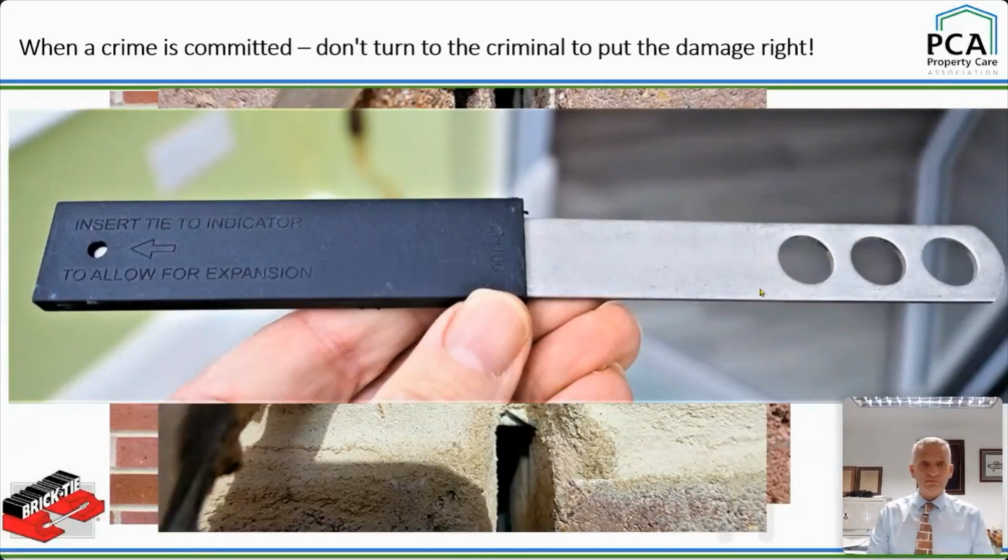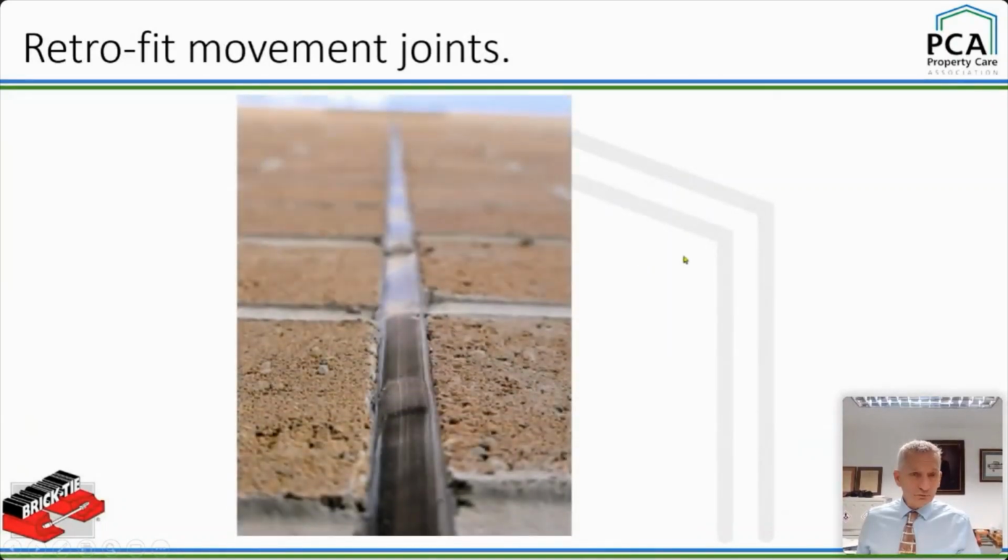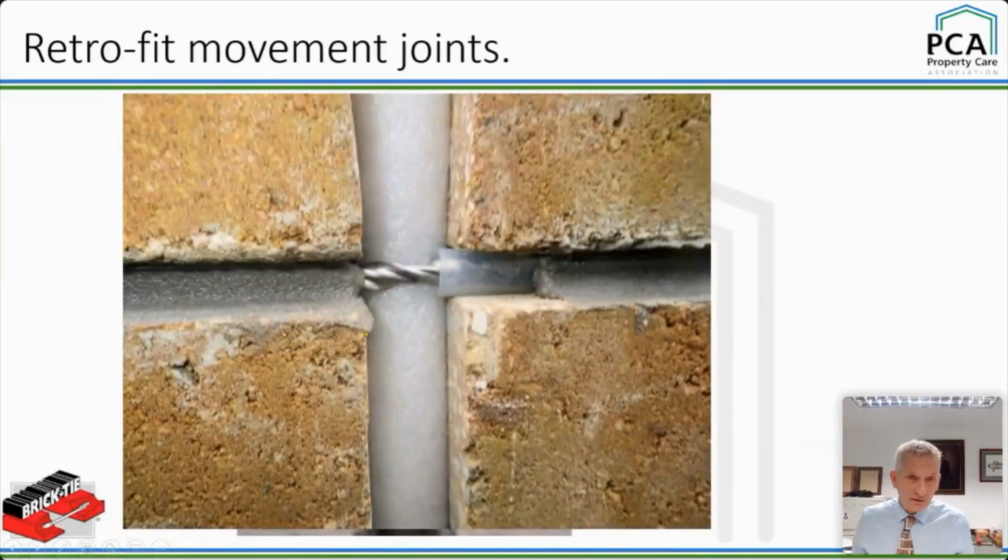The reason I've included that for you is because periodically, brickies will just remove the sleeve and throw it away because they're in a hurry, or they'll install it incorrectly, either bonding part of this across the cavity, I've seen that, or pushing this sleeve on firmly so that the metal tie, the other side here of this, is right to the back, in which case the joint can't close. So retrofit movement joint should look like that. That's a correctly installed slip tie before it's pointed away. I like to see the little tube sticking out, to be honest.